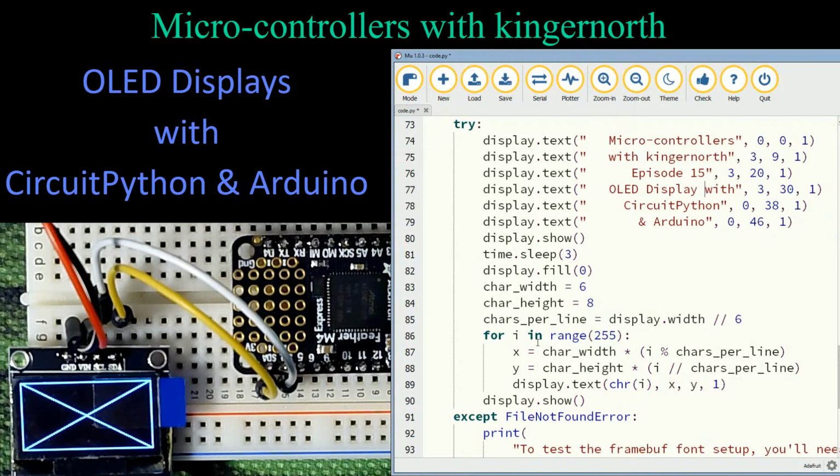Can I use this to calibrate my block occupancy parameters without a computer hookup? You could, but then you'd be leaving a display hooked up, because I2C doesn't like to be disconnected while it's running. So you could hook it up, and if you wanted to leave it that way, you could. That is another option, and you can actually have it print up on a screen what's going on with your block occupancy detector. It just adds another little feature to it, and it could be convenient, because you can create text rather than having a bunch of LEDs saying which lines are occupied, which lines are not. That'd be interesting.